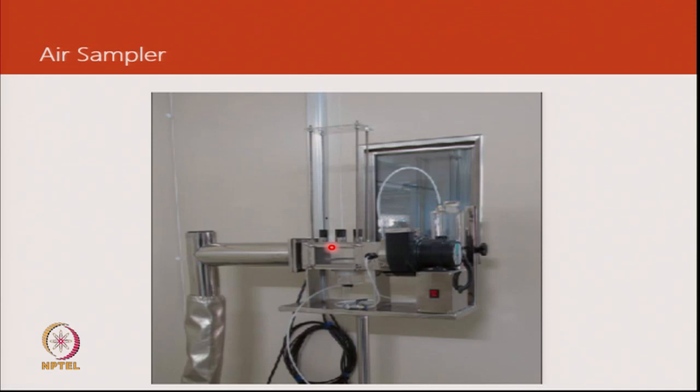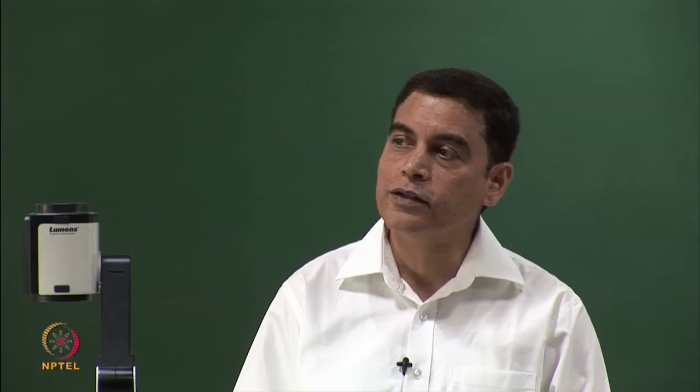So the supply air condition or the return air condition, whatever we are measuring, an air sampler like this would be used. This gives us a reliable reading of the enthalpy. It will be derived from the wet bulb and the dry bulb conditions. So finally, when we have these, then what you said about the psychrometric chart is correct. You put it on the psychrometric chart, take the parameters and calculate the capacity.